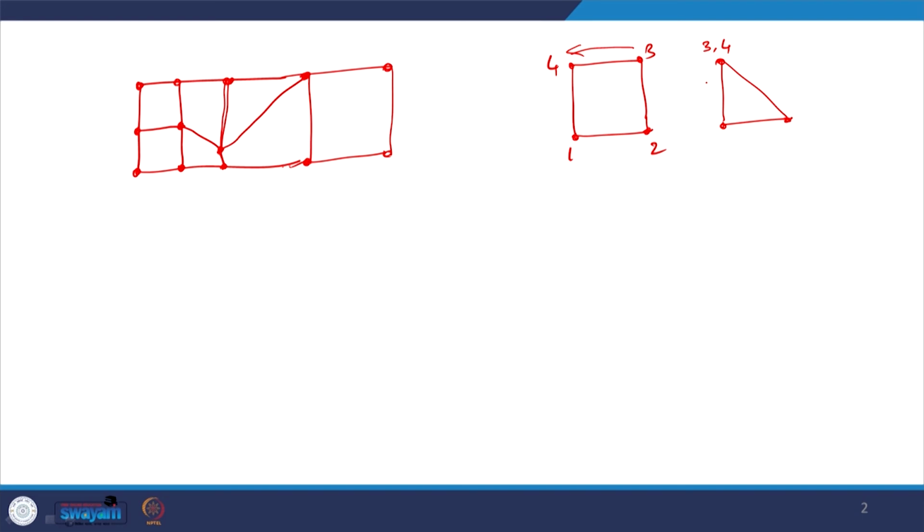If we go through the entire process of this mapping and assign the same coordinates in the physical domain for node 3 and node 4, and then compute the strain field, we will find that this 3 node triangle will have a constant strain field. So, we can generate a 3 node constant strain triangle by collapsing one corner node of a 4 node rectangle onto another corner node.